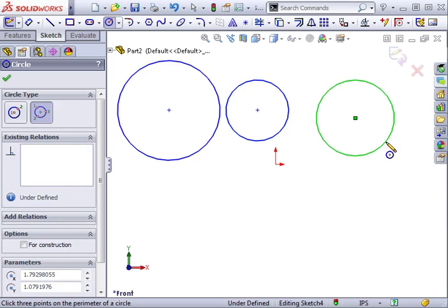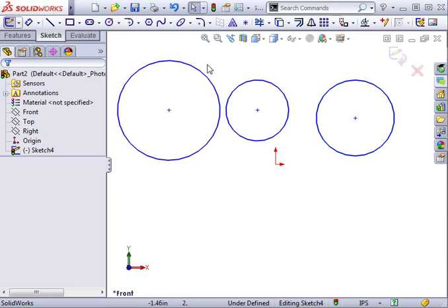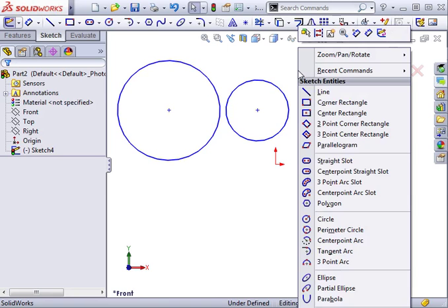There is one additional and very useful method to create an arc that does not appear on the Sketch toolbar. It's called Sketch Auto Transition and is accessed from the Line tool. Begin a sketch line and to switch to an arc, simply move your cursor back to the beginning of the line segment and move your cursor off in the direction you would like the arc to continue. Notice the Line tool has switched to an arc. You can control the direction of the arc by moving your mouse in different directions from the starting point. After completing the arc, the Sketch Line tool is reactivated.